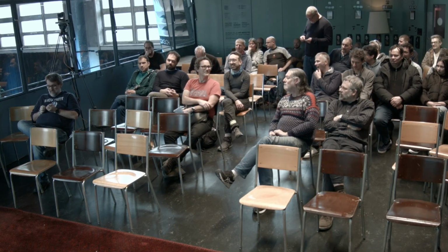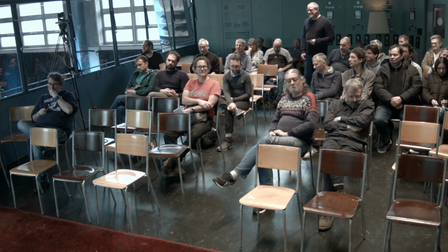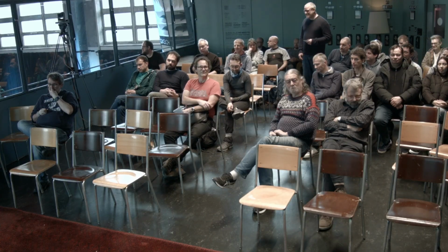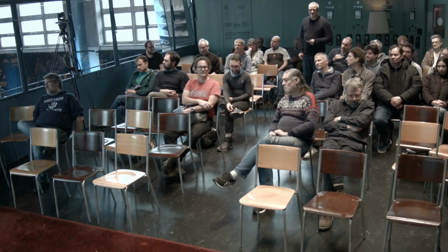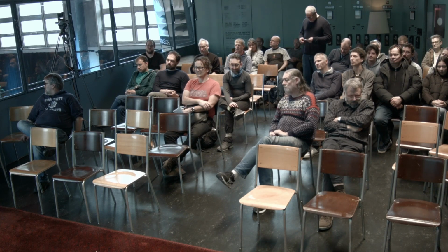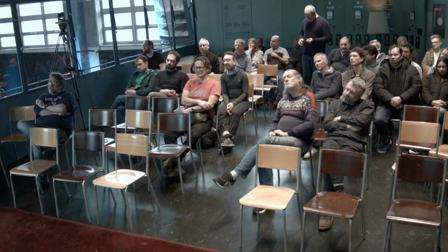So usually people have different design goals. One design goal could be cost, or one design goal could be cycle accuracy, or something like this. So there could also be another solution. You could have two of your boards, which were, I think, at $23. And then one of these boards can be the RISC-V, because there is a very low number of LUTs used by RISC-Vs, and I think a board of this would be sufficient. I can fit it inside a single FPGA.